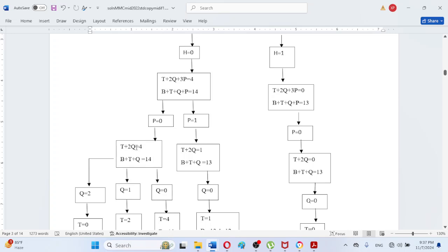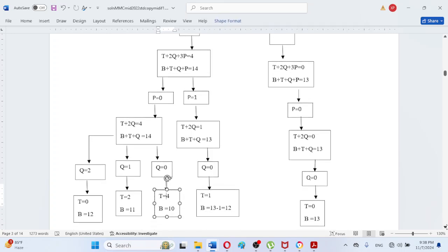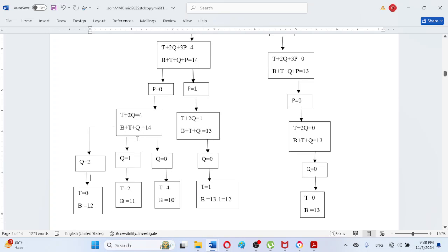Because here the highest order link is quaternary, if q is equal to 0, as we can observe, t will be equal to 4. So there will be 4 ternaries, and the lower equation will give that quaternary is 0 and ternary are 4. So 14 minus 4 will give 10. So 10 binaries, 4 ternaries, and all others, meaning q, p and hexagonal, are themselves 0.